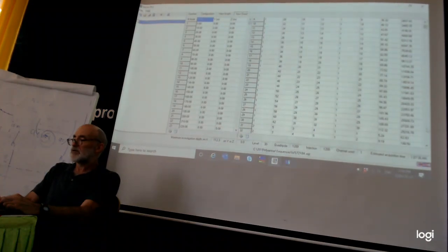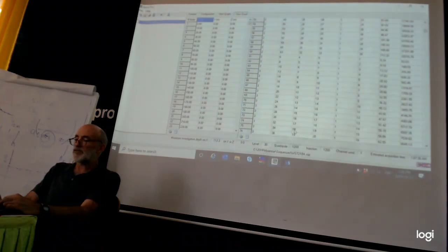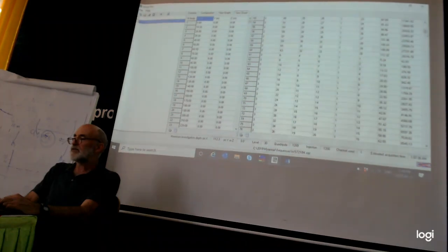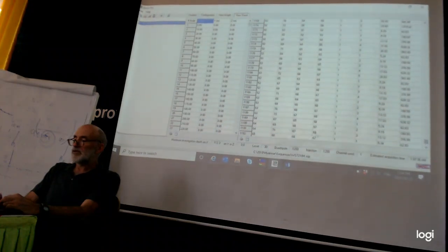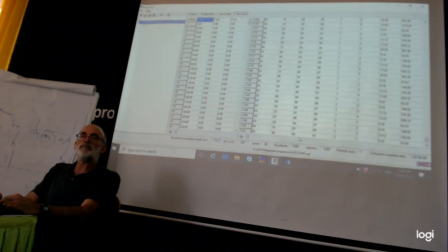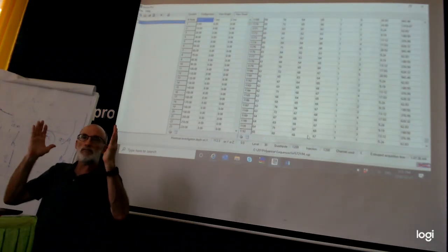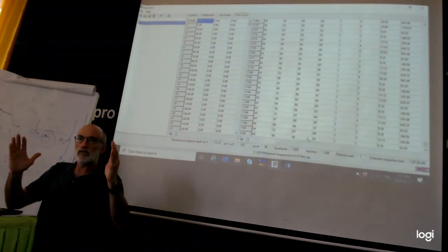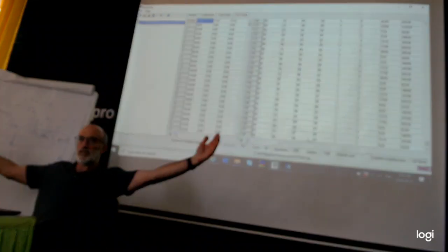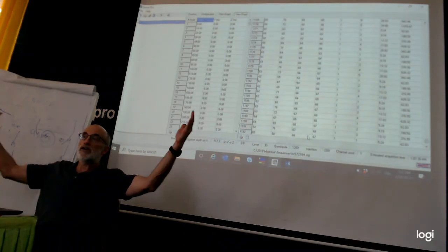See how these are just one number difference? That's the M, that's the N. And if we go through to the very end, it's still only 10 meters apart for the MN. And so the problem is that the potential voltage might not be very large between two near electrodes. But if we increase the separation between the M and N electrode, we have a better chance of measuring a higher potential voltage.